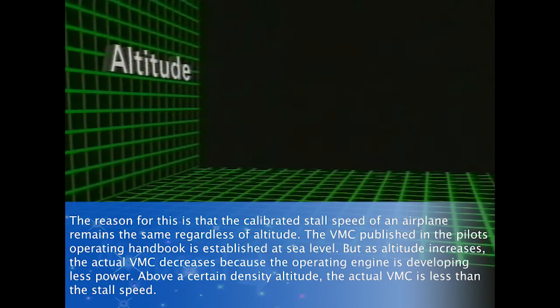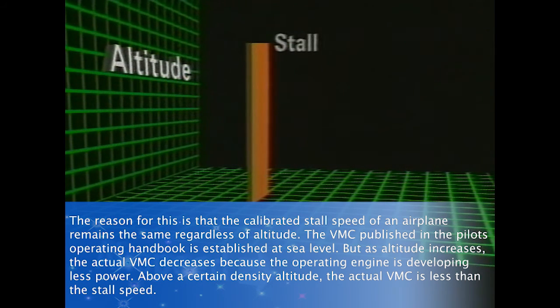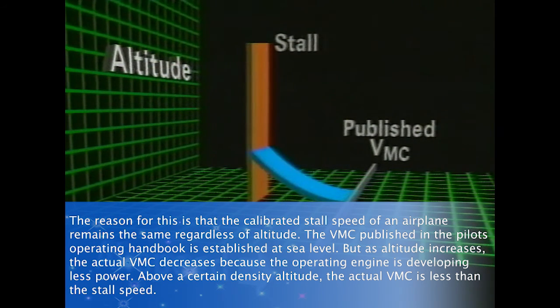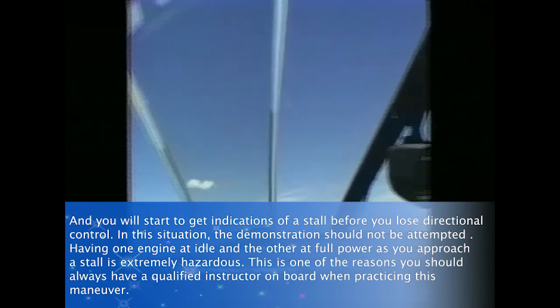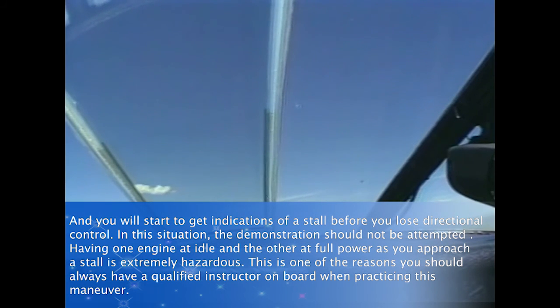The reason for this is that the calibrated stall speed of an airplane remains the same regardless of altitude. The VMC published in the Pilot's Operating Handbook is established at sea level. But as altitude increases, the actual VMC decreases because the operating engine is developing less power. Above a certain density altitude, the actual VMC is less than the stall speed, and you will start to get indications of a stall before you lose directional control. In this situation, the demonstration should not be attempted.